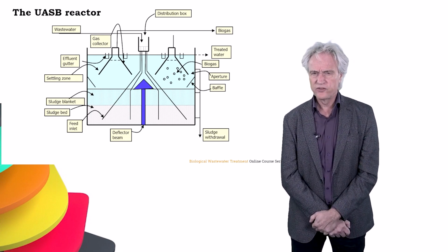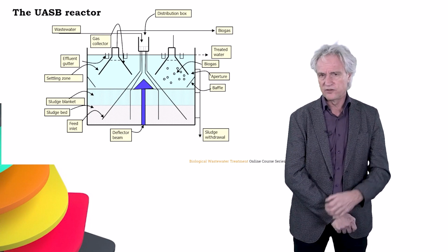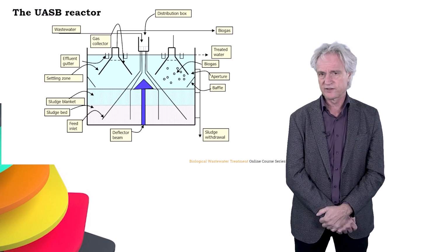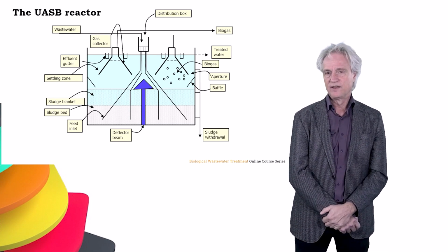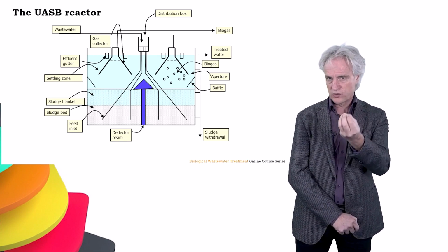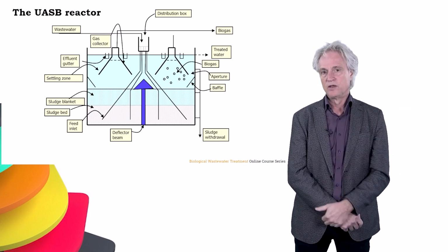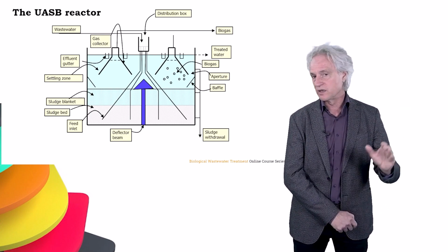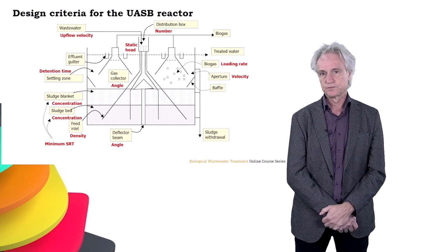Now, do realize that the distribution of the effluent is above the liquid level of the reactors, which is causing a static head. And with this static head, if there is a clogging, you will build up some water pressure in the pipe, and by the increase of that water pressure, you have, in most cases, an automatic declogging of this clogging of the influent pipe.